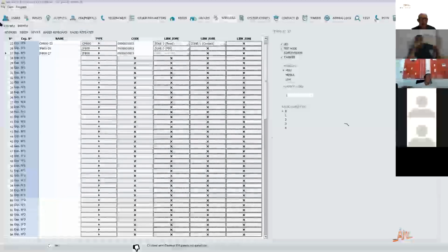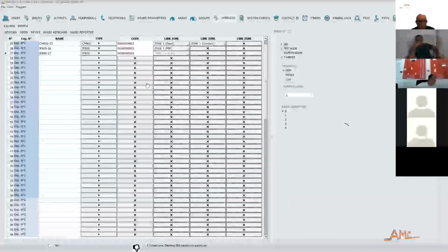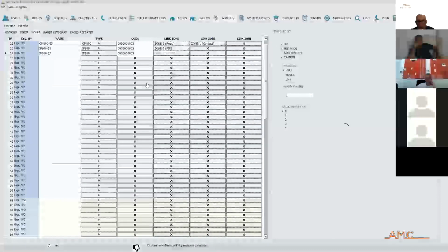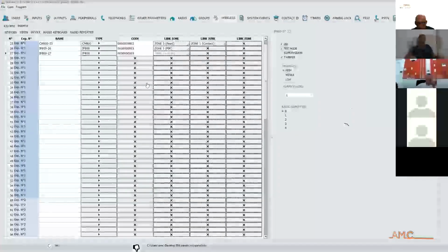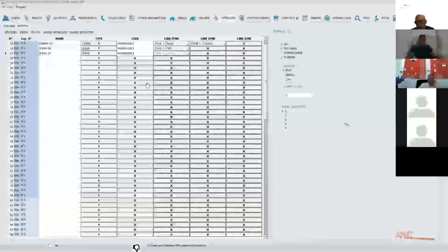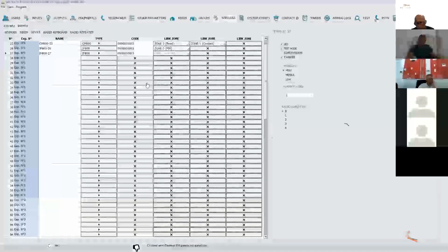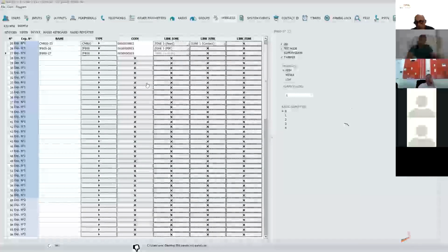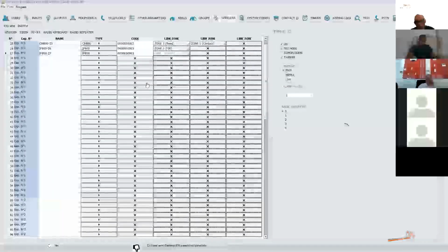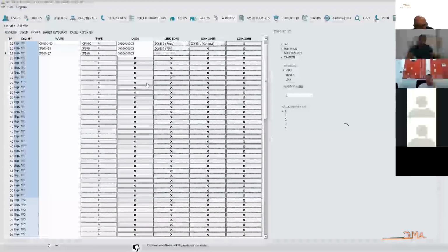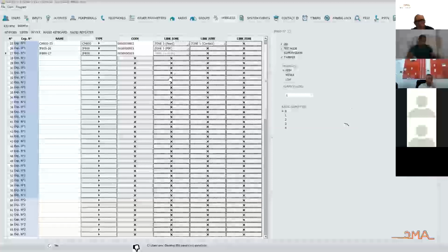No, I understand what you mean. 64 are the places of wired zones, but you can add more devices. Understand what I mean? But normally you need to think always with 64. So the total number of zones is only 64 in every panel? Exactly. Not more than 64. Exactly.